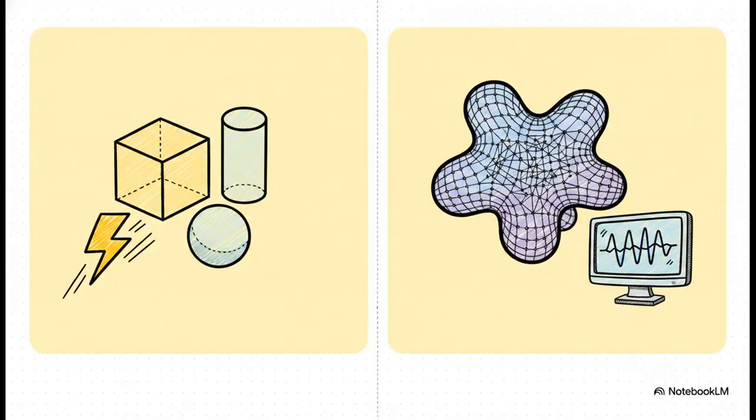So, when it comes down to it, a thermal engineer today relies on 2 primary highly practical tools for multidimensional heat conduction. On one hand, you have shape factors. They're quick, they're perfect for standard shapes, and they offer a brilliant analytical shortcut for rapid estimates. On the other hand, you have numerical methods, absolutely perfect for highly complex shapes, relying on dense nodal grids and powered by heavy computational software.